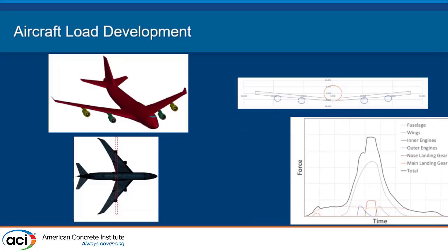For this, the load is an aircraft impacting the structure. There's different ways to do this. I've done it from very detailed aircraft models impacting structures to this kind of approach, which is called a modified Riera approach, where we are applying the load separated in space and time and developing these curves that are shown, force versus time, by slicing the model axially along its length and apportioning the mass in different buckets for like the engines, the wings, fuselage, and using F equals ma kind of inertial change in momentum kind of calculations to come up with the forcing functions.